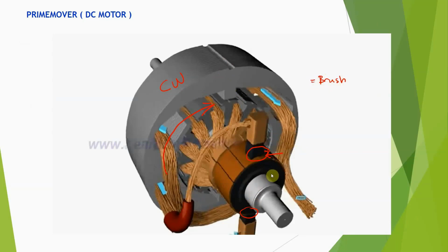And also there is a friction due to the bearing here. So if our direction of rotation is clockwise, the direction of friction here is counterclockwise. So we have friction due to bearing. And there are two bearings here, one at the front, of course, and one at the back. And another cause of friction here is the wind friction.